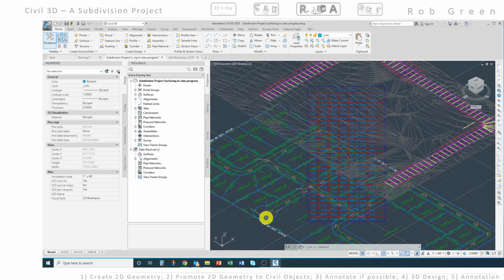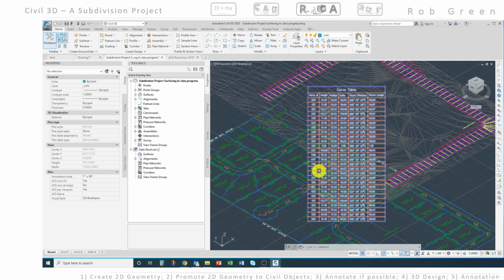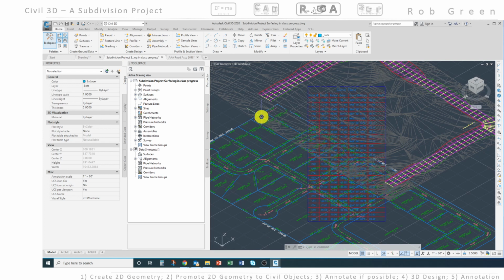And if we don't rotate into 3D and look and see what our 3D elements look like, then we never get a chance to see that because it doesn't show up in plan view. So now that we're working in surfacing, it's important to execute a command, look at it in 3D, and verify that what we think we commanded is actually what happened in Civil 3D. Okay, so let's navigate back to the top view.